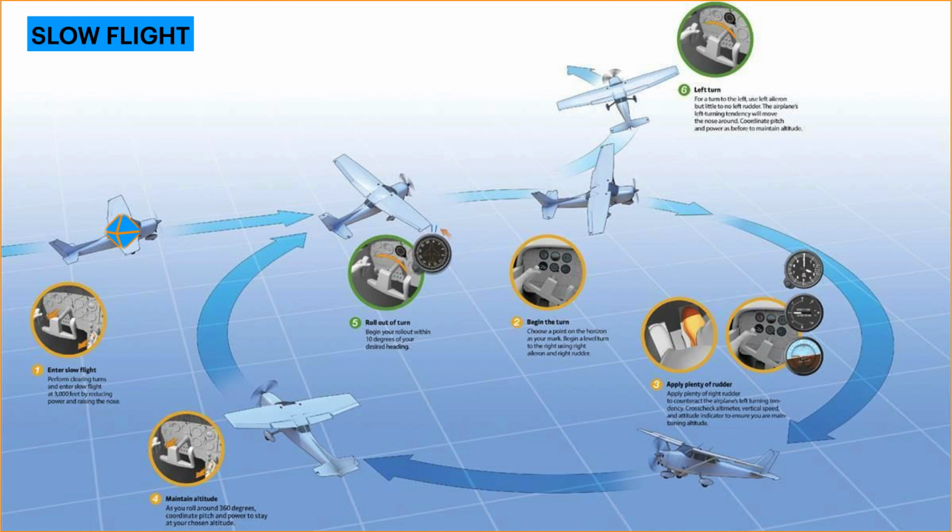As you enter slow flight and flaps are added or retracted, anticipate pitch changes and associated changes in lift. Remember, it is very important to remain coordinated in slow flight, so in the event a stall occurs, it minimizes the chance of entering a spin. At high angles of attack, your horizon reference over the cowling may be obscured. Scan left and right and at your Lindbergh reference for traffic and visual clues as to the airplane's condition.